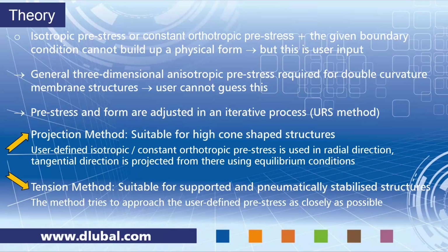And you as a user can set the number of iterations, that is, up to when the pre-stress adjustment stops. So you can change the number of iterations, and you can therewith influence the final form that you calculate.